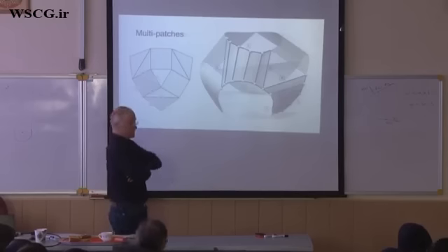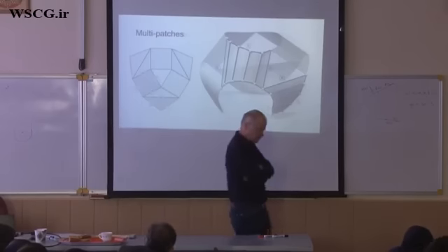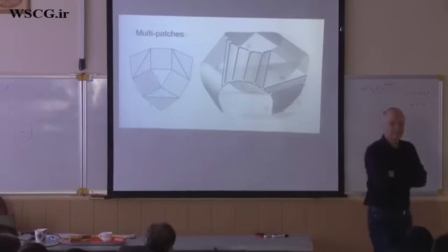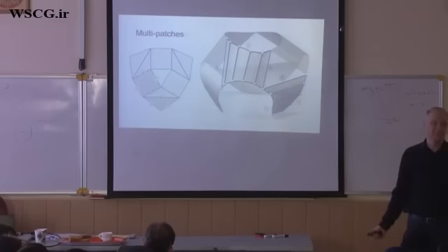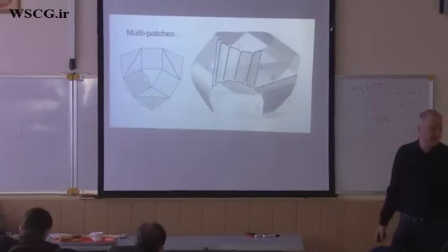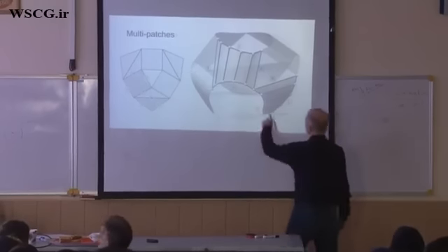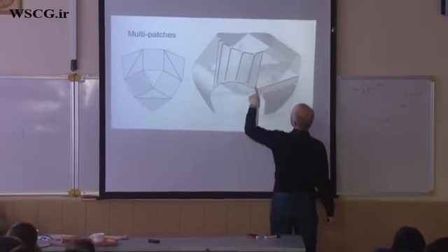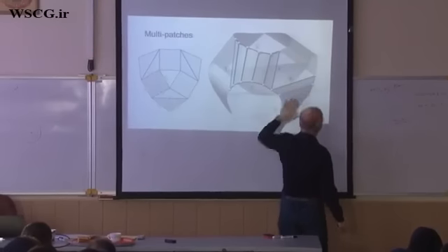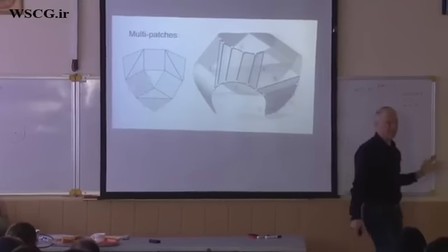Now, the thing is more complicated, because if you would really like to model developable surfaces, you will not work with one Bézier patch. I mean, this is nothing. You need B-splines, and you need these nasty connections of planes with smooth patches. This will pop up in practice.